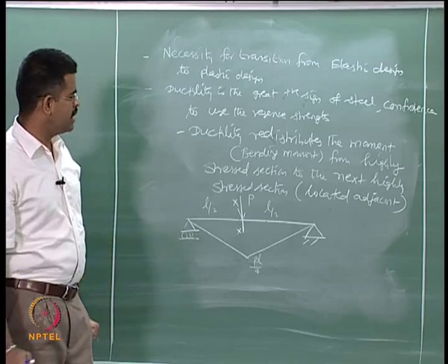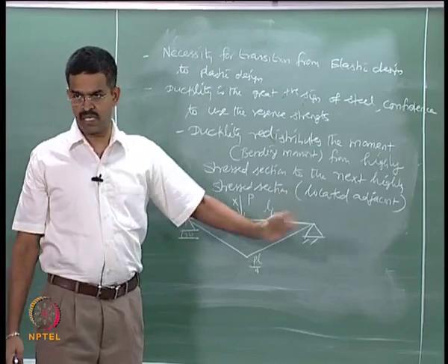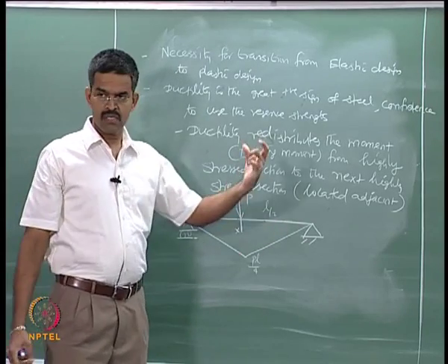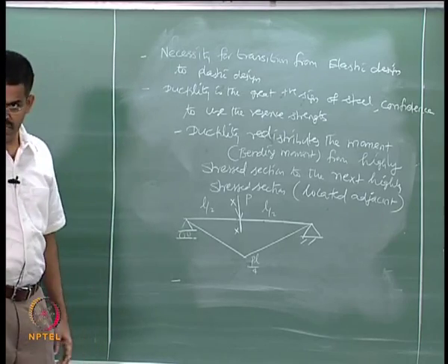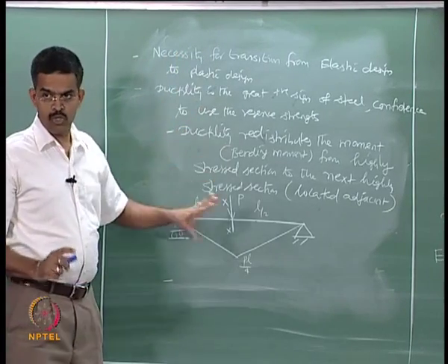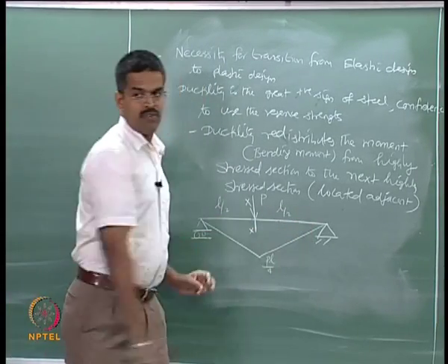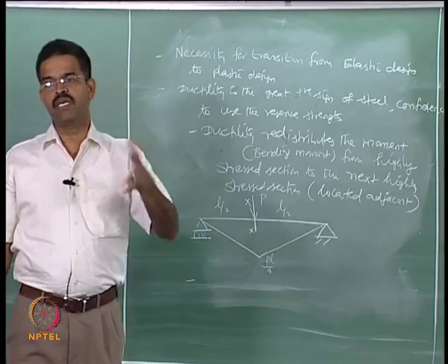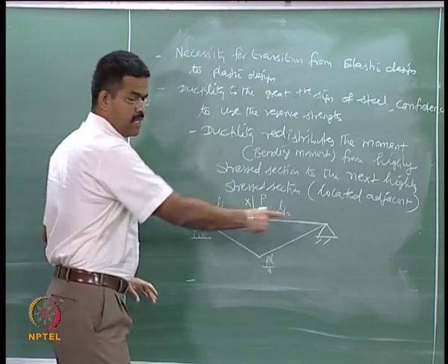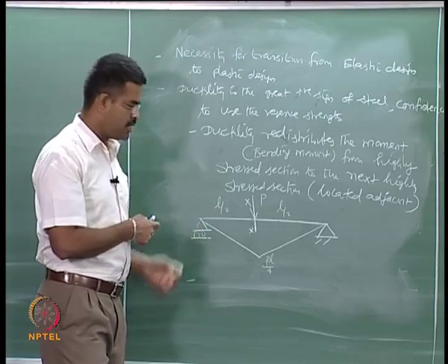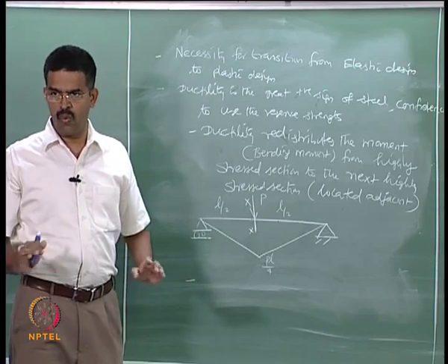Now, interestingly, you will be trying to find out what would be the next highly stressed section as far as this beam is concerned. There is a very important precondition that this design process should be applied and can be applied only to structures which are statically indeterminate. This is a determinate structure. The degree of indeterminacy for a simply supported beam is nil, is 0.